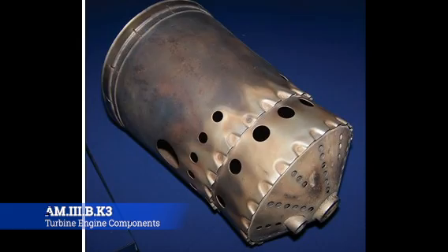We also need to burn the mixture efficiently. That means there's a certain size and shape of the flame that needs to happen right there, and you'll start to see different power ratings and different EGTs, TGTs, if things are off just slightly in the combustion section. That could be as simple as the spray nozzle being all coked up, or maybe the can not sitting quite correctly, and so you have to go in there and fix these things after you do an engine service.